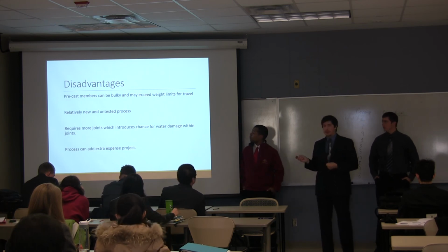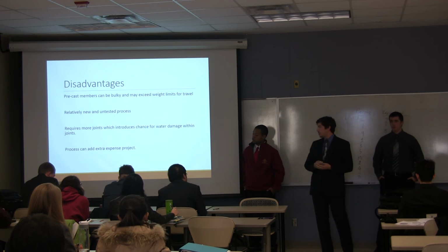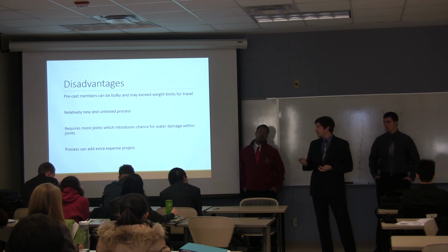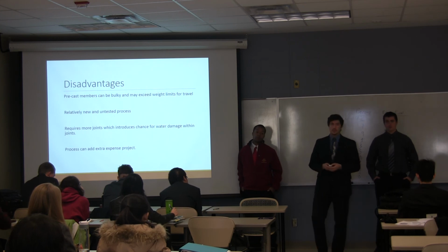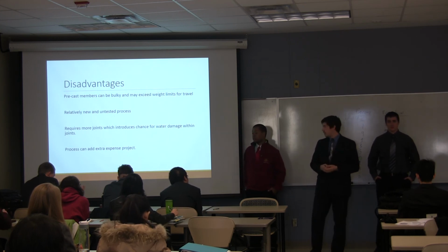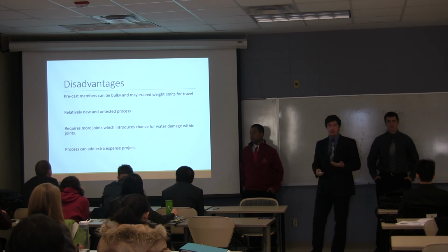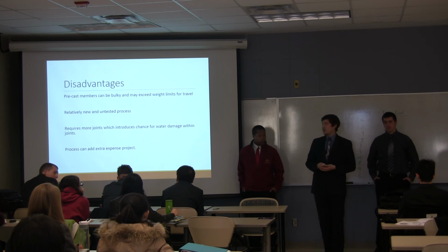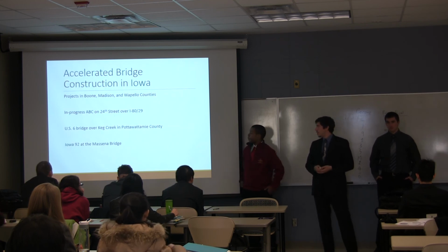And with the prefabricated method, there's a lot of joints that go along with it, and more joints introduces more chance for water damage within the joints. So freeze thaw can be a problem with that. And sometimes, since it is a newer process, they're still working out reducing costs, but in the long run, it reduces the overall project time, which is saving money in the long run.